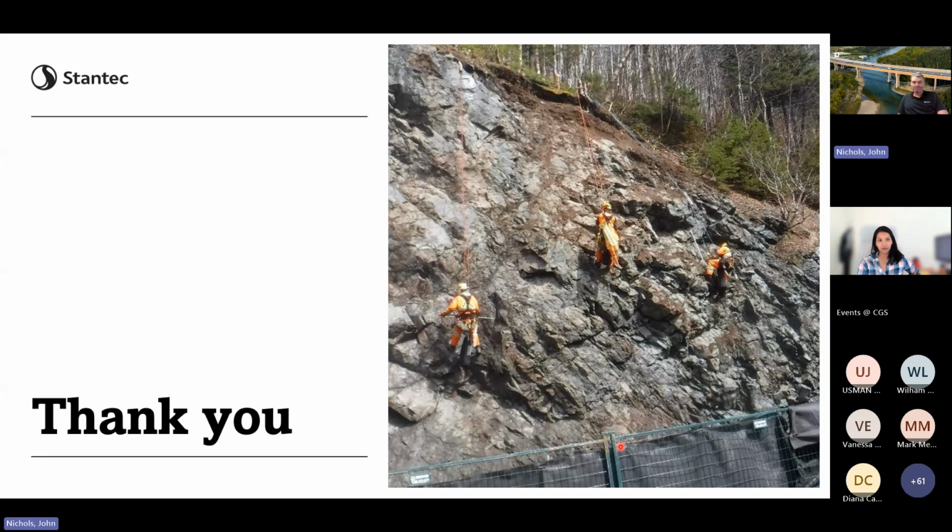But again, shale would be a good one, because sometimes if it's a very weak material, and it's not dipping out of the face, maybe it's an intact rock strength parameter. So I would start with the orientation, and then I'd start with understanding the intact rock strength.